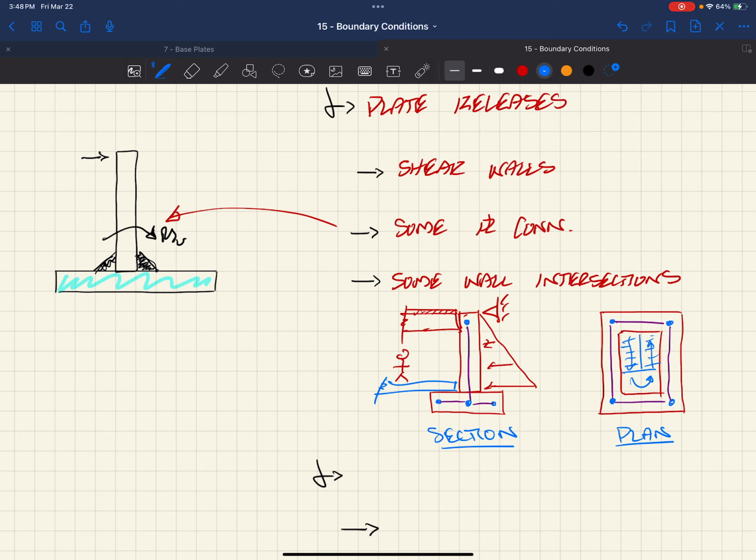I've talked about this briefly in class before, about continuity around corners. So if we have these four plates and we connect them at the corners and we push, this thing looks like a big stair tower, it's a big tube, and all of a sudden we put horizontal load on this tube, right? It's going to tell us, as we know, if there's continuity across this corner, that there are going to be compressive stresses that exist around the corners.